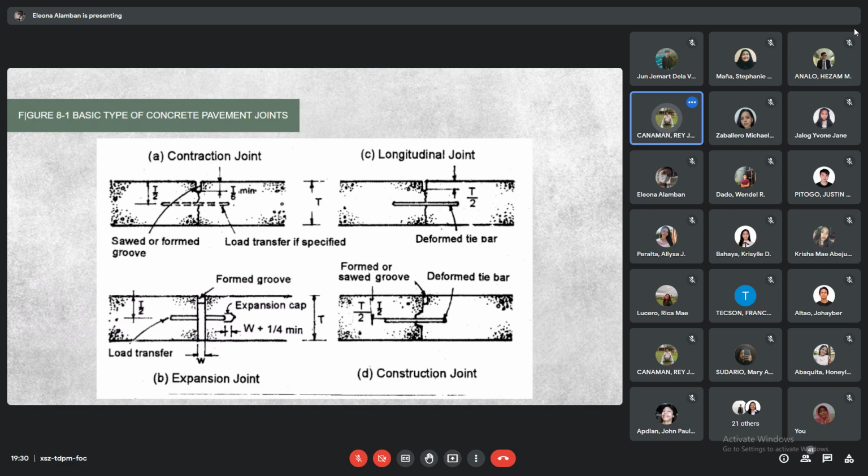So first of all, concrete is not a ductile material. It doesn't stretch or bend without breaking. But concrete moves, shrinks, and expands, and also different parts of a building move in different ways. So this is where joints come into play. When concrete moves, it is tied to another structure or even to itself. So we get what's called restraint, which causes tensile forces and invariably leads to cracking. So next slide, please.